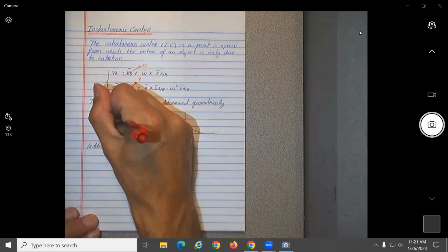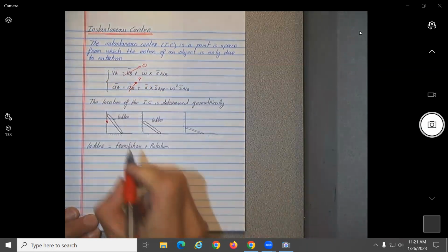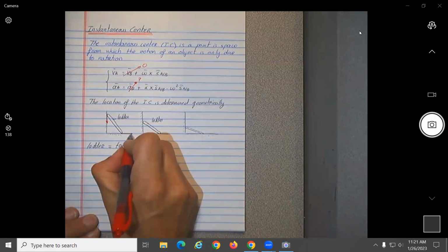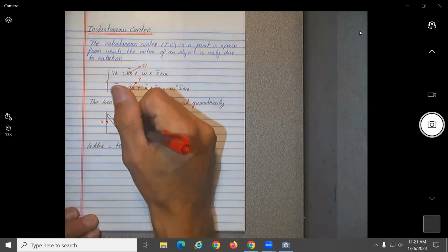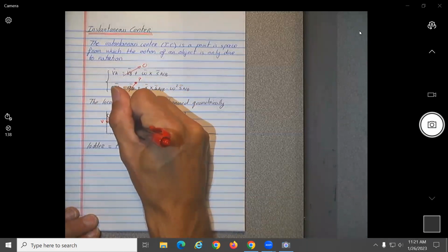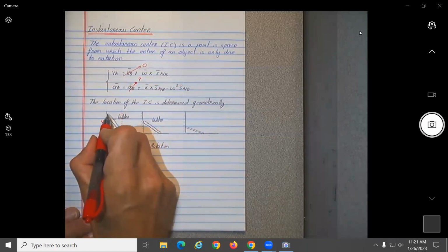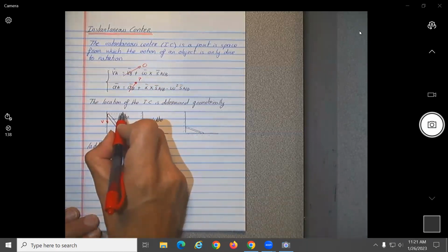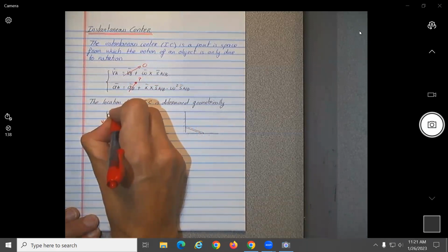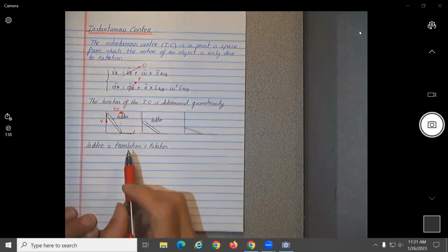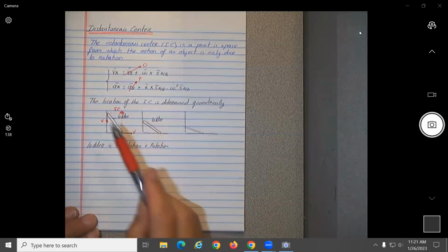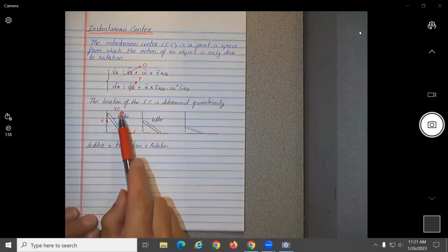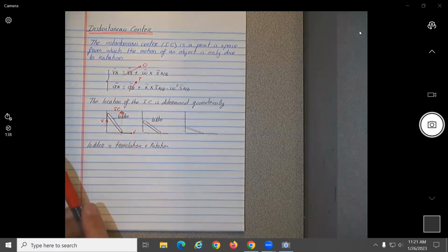We take the velocity of this point down and the velocity of this point going to the right. From the origin of the velocities, we create a perpendicular and look at the intersection. At that instant in time, that point of intersection is called the instantaneous center, and you can study the motion of the ladder as if it is just due to rotation.